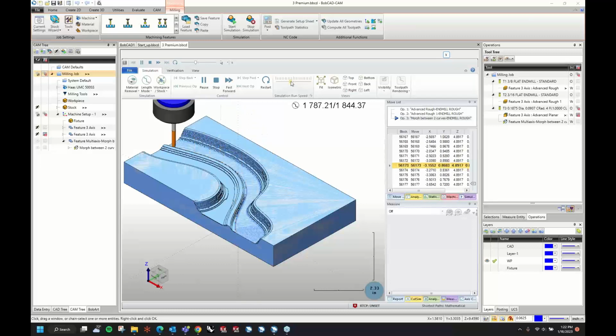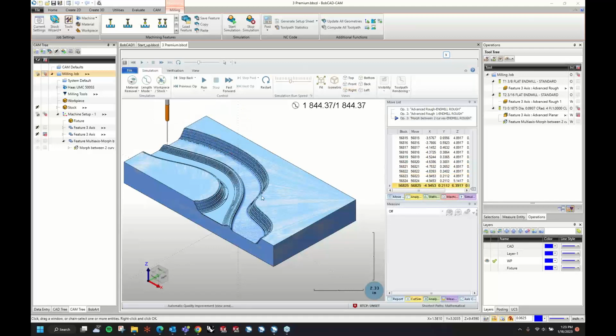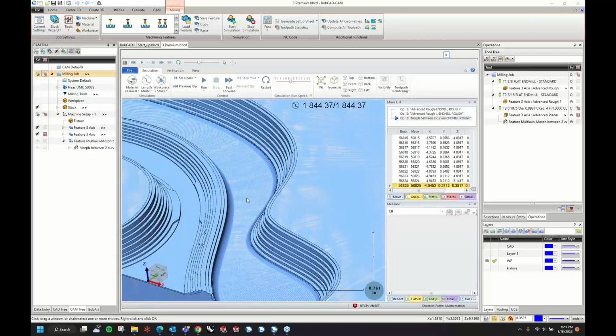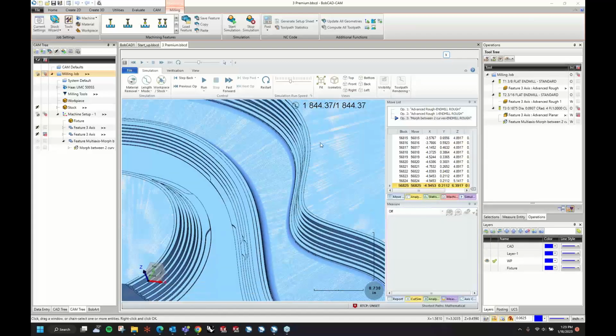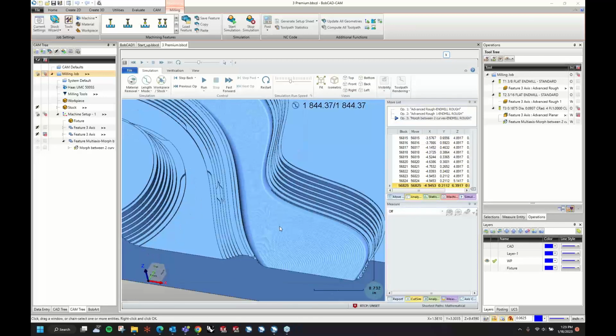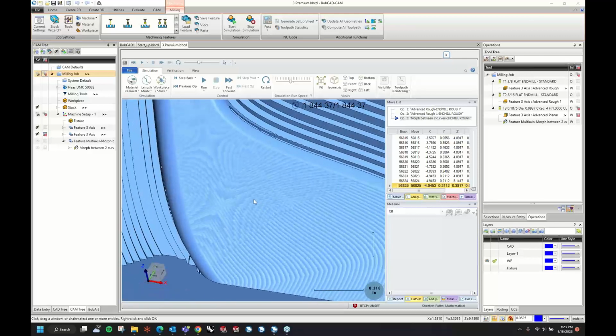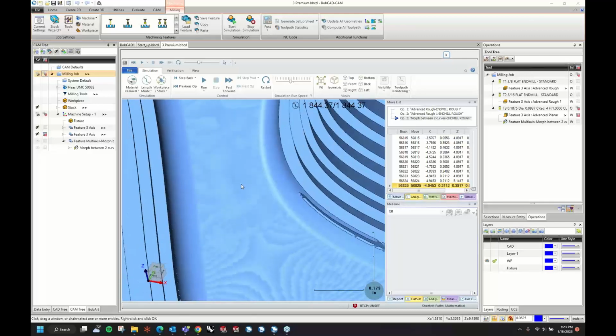Now, this toolpath does have the option for an exact step over if you need it, but it's really made to morph between the two sides. So you're getting a much more consistent finish all the way across. And it's going to be a little tighter in the middle. And if I turn off my workpiece, we can see that the cusps get a little wider toward the entrance and they narrow down coming in, because it's just morphing between those two and doing the exact same amount of step over throughout the whole path.